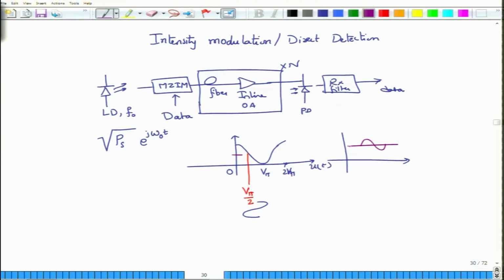This is about half on a normalized scale, and any time varying modulation signal that you apply will be generated at the output. And this type of modulation, as we have emphasized many times, is called amplitude modulation, and it is one of the classes of what is traditionally called continuous wave, linear modulation or analog modulation technique.